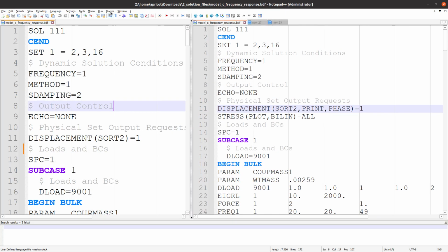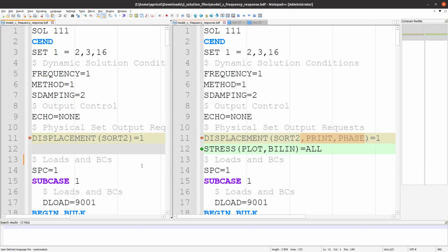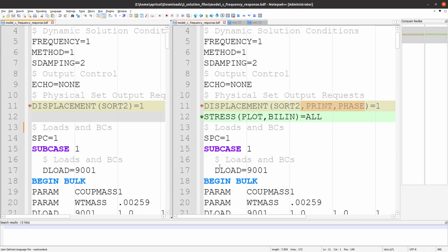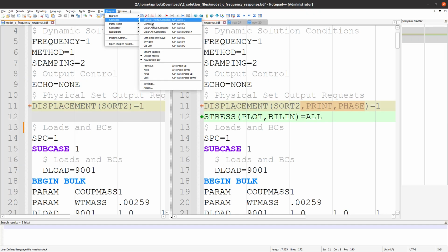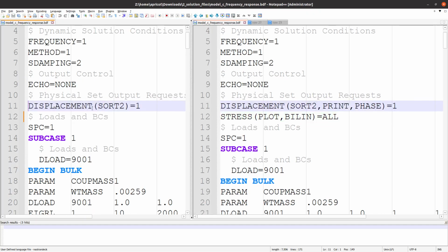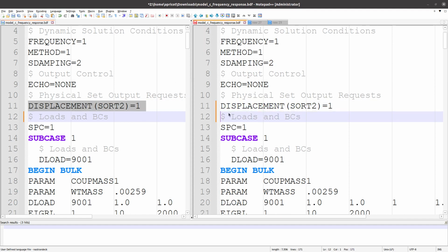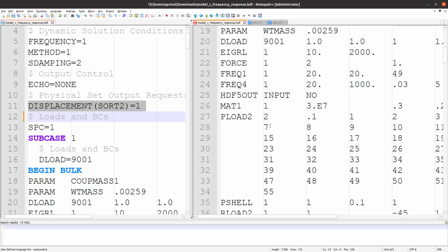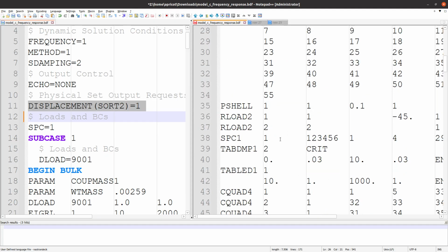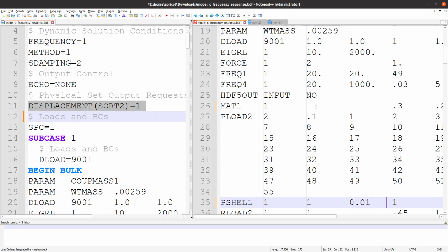So when you compare this, you can use the result of the comparison to determine, okay, I think I might have made a difference here. I'll give you another example. Let's suppose that for now there was a 100% match. Let's suppose that when we did the exercise, we forgot a few things. We forgot to specify the Young's modulus, and we forgot to adjust the thickness. So we'll go ahead and change the Young's modulus and the thickness values.